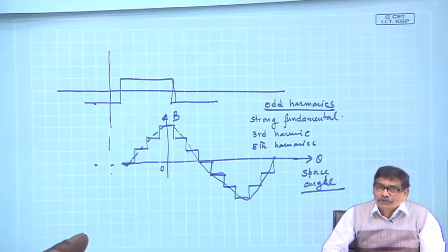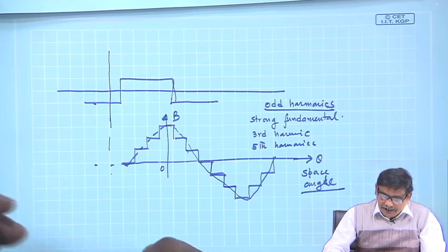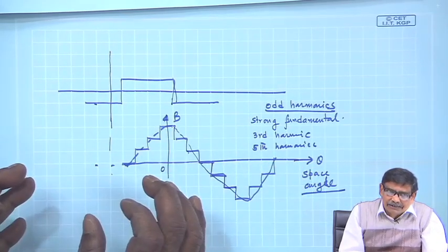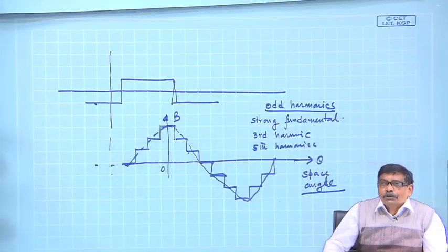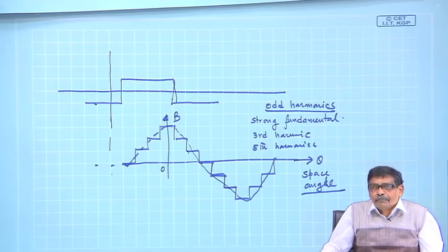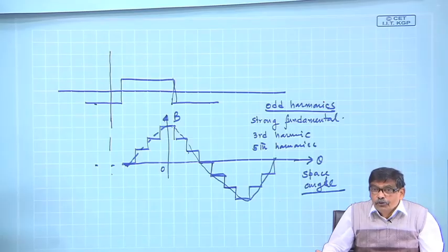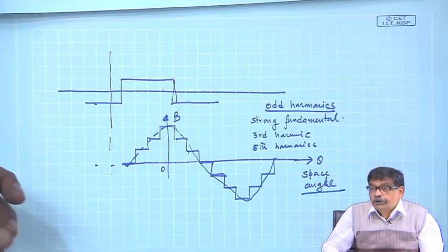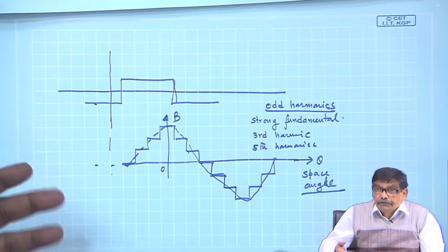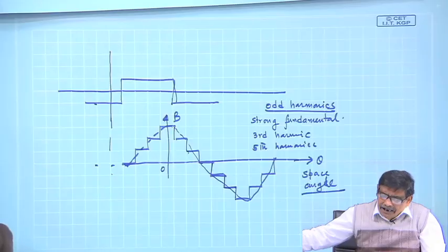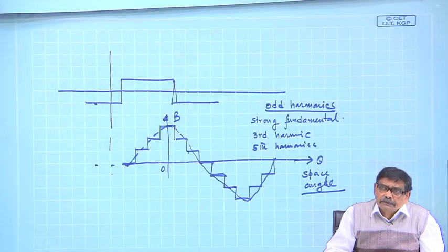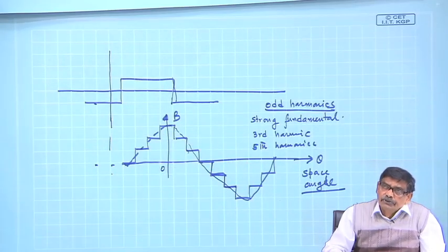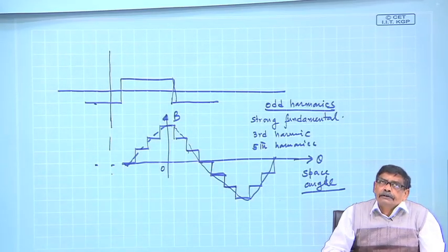Then we have many things. I mean, first thing is you have made it more sinusoidal, then you are telling I have done this so that the third harmonic will not be there. Third harmonic is the most predominant harmonic. The most predominant harmonic will have the highest amplitude among the harmonics. So, if you can neglect that, then okay, higher order harmonics can be eliminated. Therefore, this is how a sinusoidal B distribution will be obtained, and